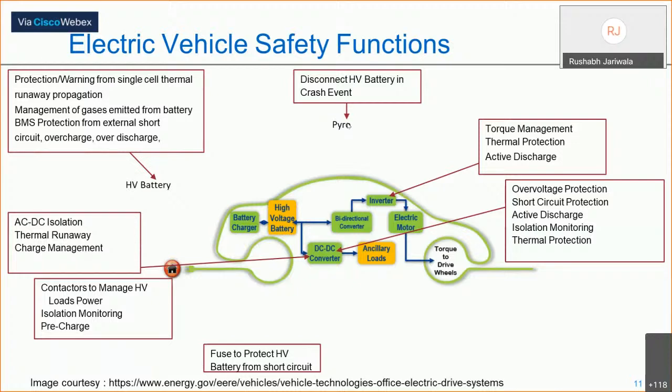Imagine that it is a switch: when there is a crash event, then inside the pyro switch there is a small charge that disconnects the battery from all the loads. So that's what happens with the pyro switch, and that is a very important device considering crash protection.